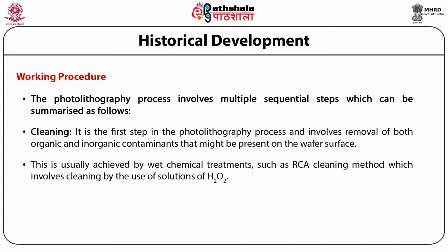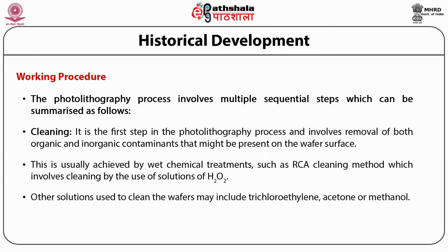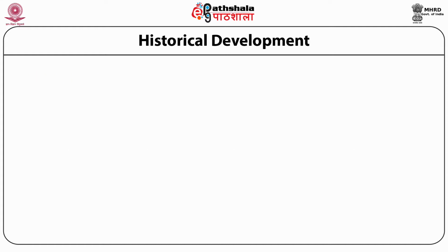It is usually achieved by wet chemical treatments such as the RCA cleaning method, which involves cleaning by the use of a solution of hydrogen peroxide, that is H2O2. Other solutions used to clean the wafer may include trichloroethylene, acetone or methanol.